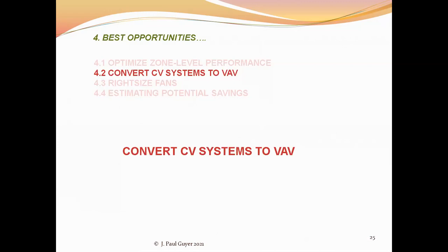VAV systems also cool only the air volume required to meet demand rather than meeting demand by simultaneously heating and cooling large volumes of air. To determine whether the existing system is VAV or constant volume, of course, review the original design drawings.